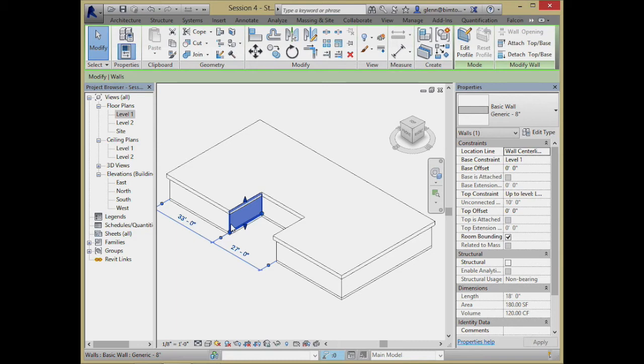Relatively mild in the scheme of things. If I just looked at the Title 24 requirements, they would want either R13 or R19, something like that. If it was a house, they'd want R13 or R19, somewhere in there. It's not incredibly cold outside, but something like that.